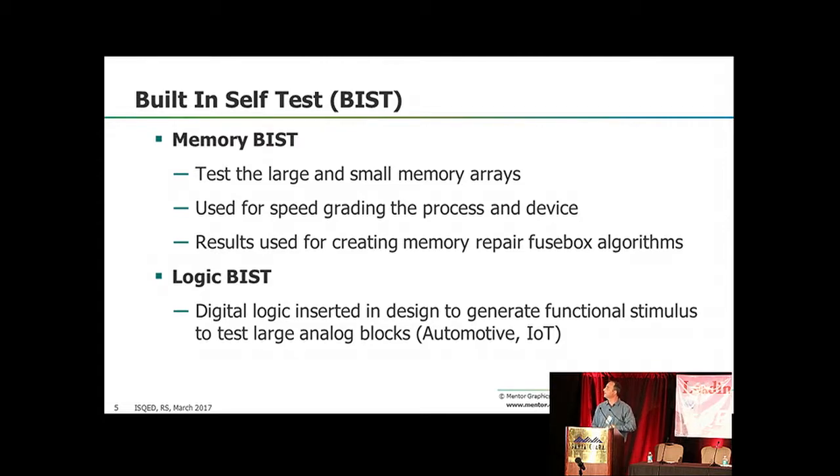Okay. Memory BIST. Memory BIST is inserted logic, just testing the large arrays. On the ATE tester, when the pattern fails, you can use the output of the XY coordinates of that memory to go back and generate a new pattern to program, let's say, your fuse box, to blow the fuses, to insert redundant arrays to increase yields.